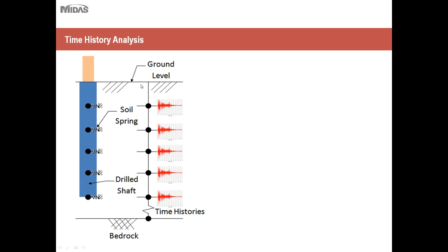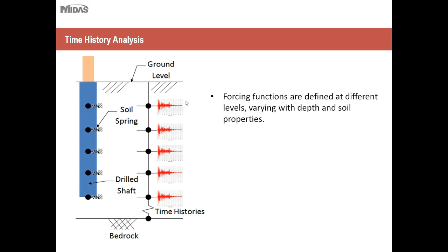Going on, something that's very unique about seismic analysis in general is the use of soil springs and forcing functions as well. Here we have an example of a driven shaft pile or a drilled shaft, and here we have several soil springs modeled on these nodes.